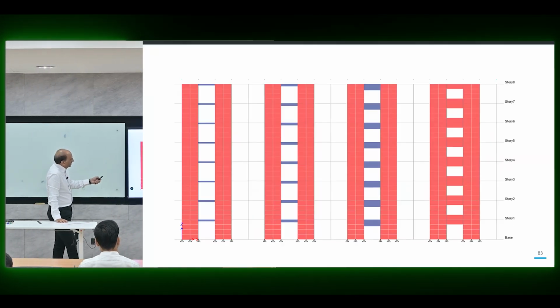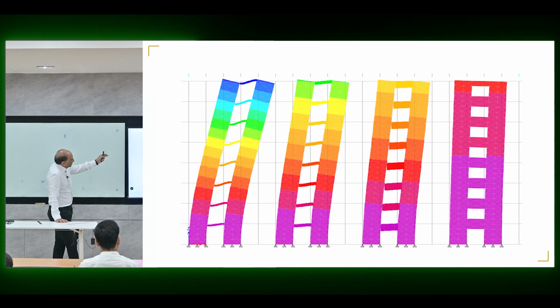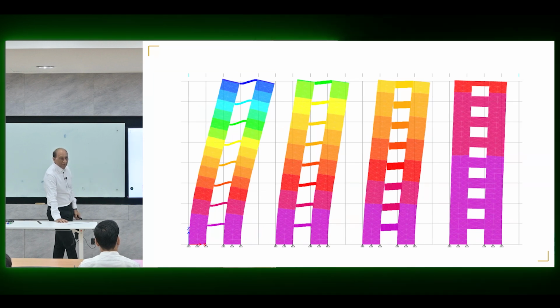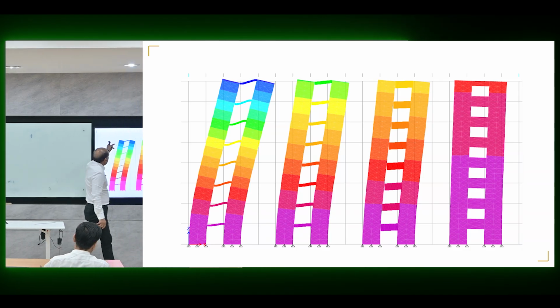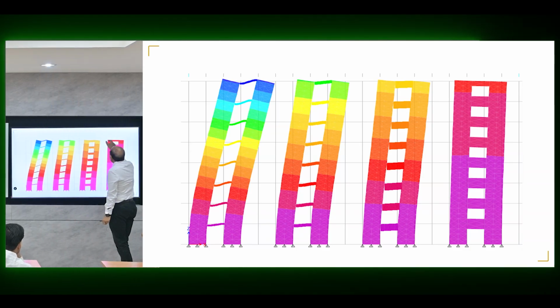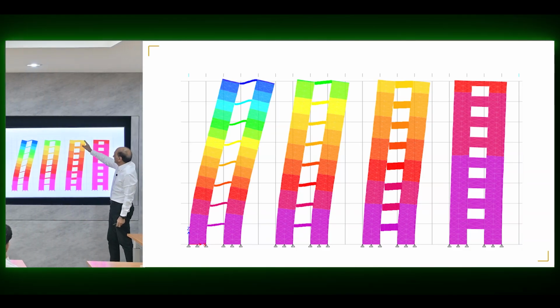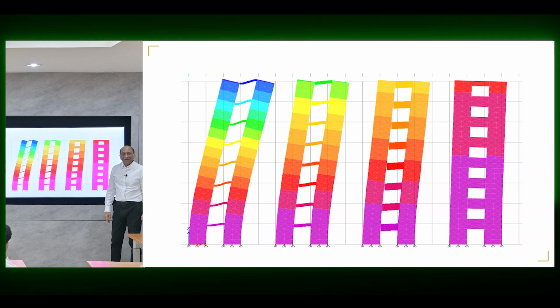You get this one, and then you get this one. Look at the deflection drift control. So much drift has been controlled. Here, drift is like this much. Here, the drift is only 1/3 or 1/4 or even less than that, 1/5, 1/6 of that, right? So you have increased the stiffness by 7-8 times by simply using those coupling effect, right?